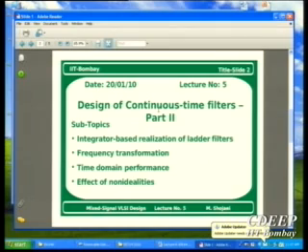And also we want to have proper constraint on the sensitivity of the filter to different voltage and temperature variation parameters. So this creates some limitation, that doesn't give us freedom to choose whatever filter we want. Of course, other issues, for example if we want to be low power and other specifications, will also come into the picture. So we will look at this integrator base as a base to learn, and the remaining part you can learn on your own, but the concept will be similar.